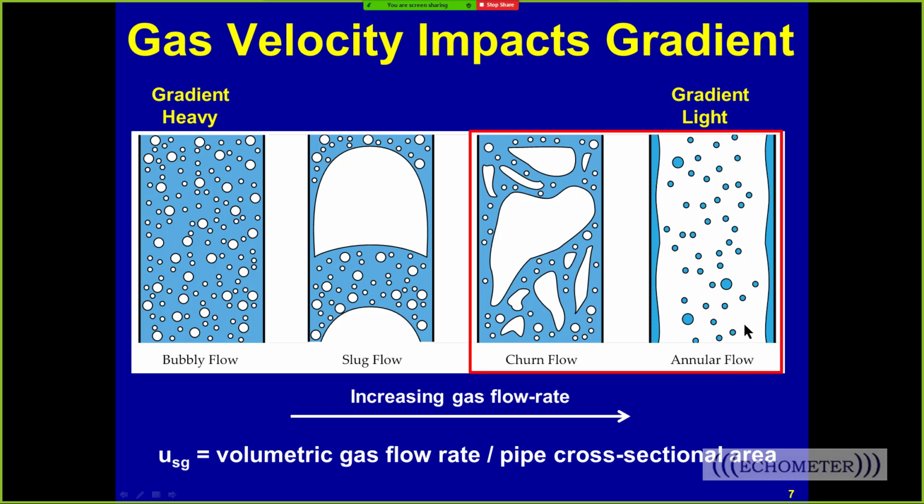On this side of this plot, we've got annular gas flow, which means the liquid film is on the side of the tubing, which is normally above critical rate. And the film, if you're above critical rate, is going up, meaning it's unloaded. If the film reverses, then little droplets of liquid start to fall off the well. The droplets are typically fairly large, and they fall down, and the film goes down and accumulates in the well and starts to load the well up.